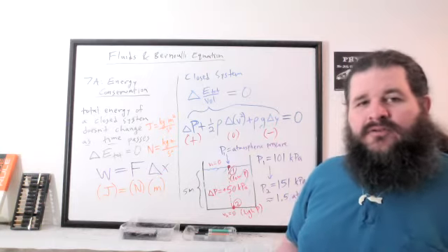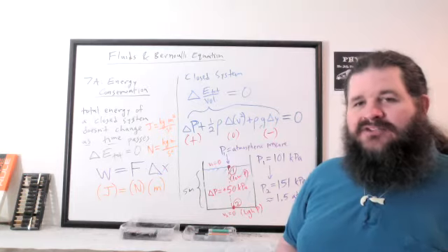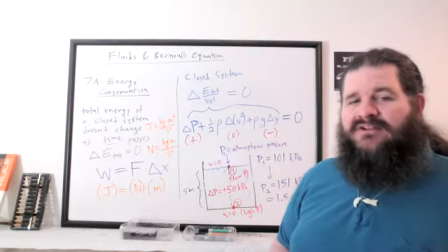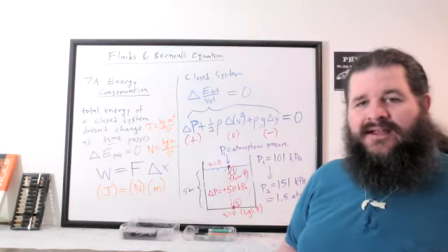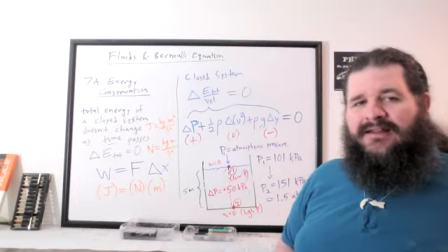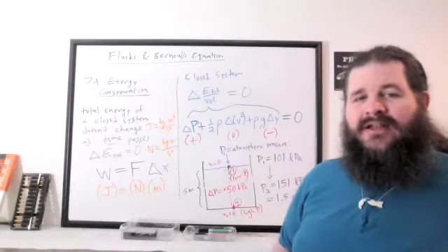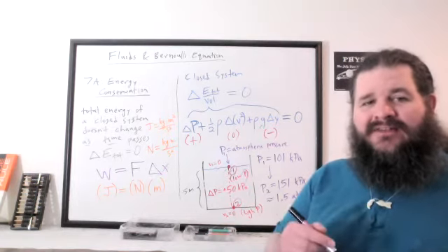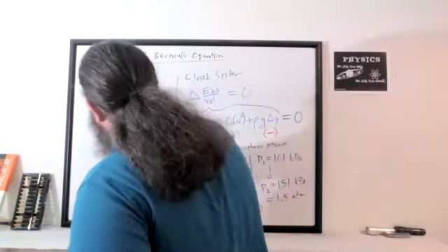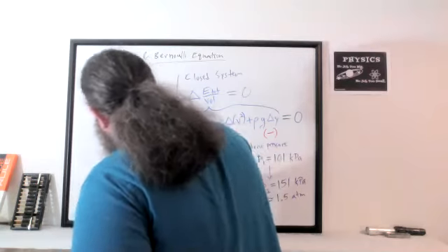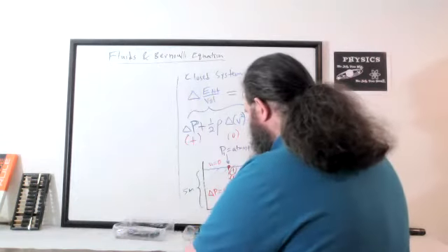And in fact, this is true for any measurement of pressure. You can't really measure pressure directly. You can measure differences in pressure. When you attach a pressure gauge to a bicycle tire or a car tire and it tells you what the pressure is, it's not really directly telling you the pressure in the tire. It's telling you the difference between pressure inside the tire versus pressure outside the tire. And this is what we call a pressure gauge.